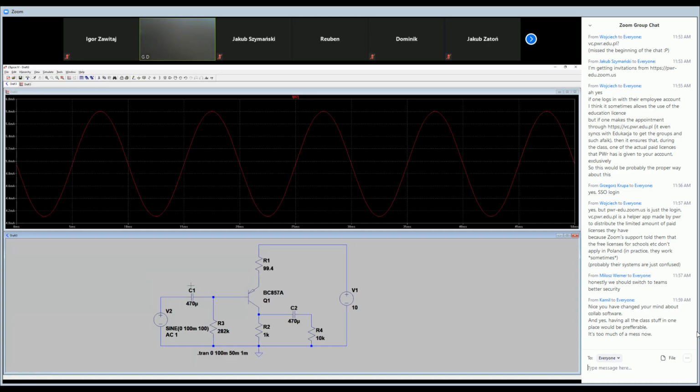All right. So I want to show you also that this voltage drop, which was around 5 volts as a voltage drop on the collector emitter, it is here. When we plug in the input signal, this voltage drop on this resistor are changed also. Yeah, of course. That's why we are observing the voltage signal output on the load resistances.